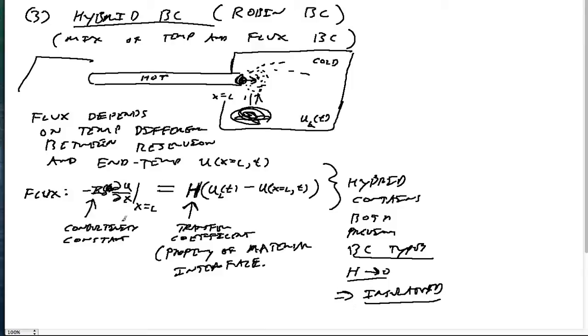Here the heat flux through the end will be 0. Okay, and that basically means that there's essentially no transfer of heat. So that transfer coefficient being 0 means that there's no transfer of heat to the outside. Okay. Now, take the other example. What if we take H to get really big? In this case, we could also put K going really small. But the idea is that it's the relative magnitude of K0 to H.